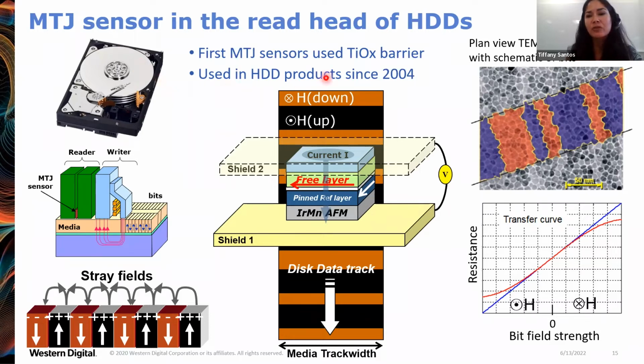And if you take a powerful microscope, like a TEM, transmission electron microscope, and you look at this shiny film surface, you'll actually see that it's a network of magnetic nanoparticles, and groups of them are magnetized together to form a bit of data, so the zeros and ones, and that's shown schematically here in the red and the purple colors, showing the zeros and ones written on a track on the media surface.